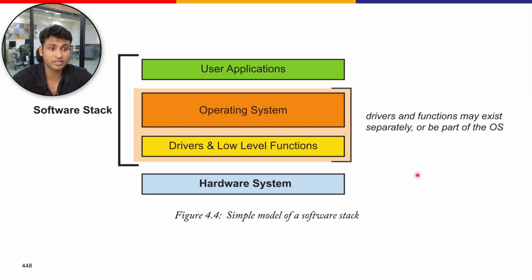which are possible in Zynq MPSoC than in the previous model Zynq 7000, which just has a dual-core APU, because here in Zynq MPSoC we don't just have an APU, we have an RPU as well as a GPU, and the PL is obviously there.